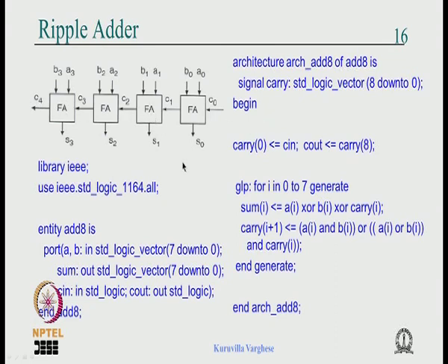Okay, and the issue with this ripple adder is that if you take the C4 or sum 3, it uses C3. In the worst case, the carry propagates from C0 to C1, C1 to C2, C2 to C3, and C3 to S3.